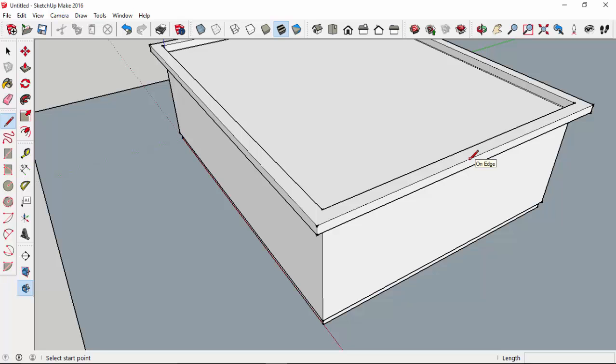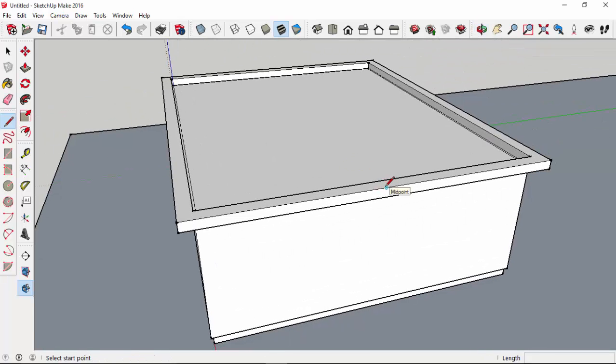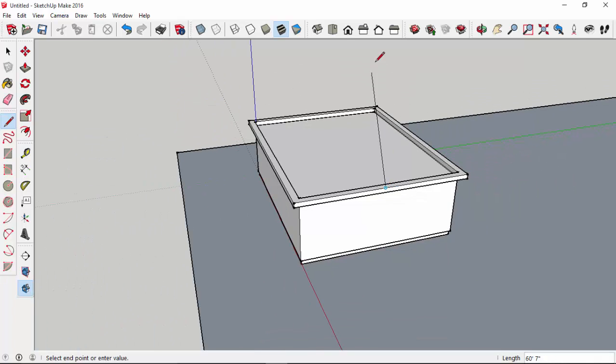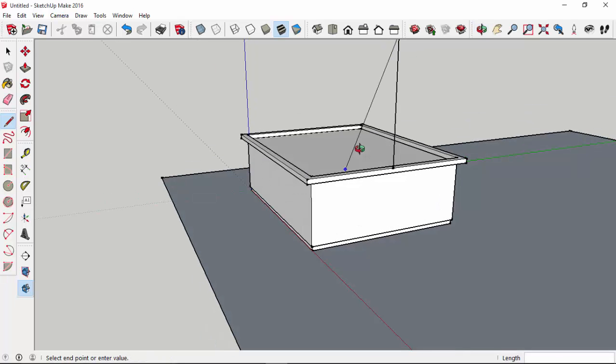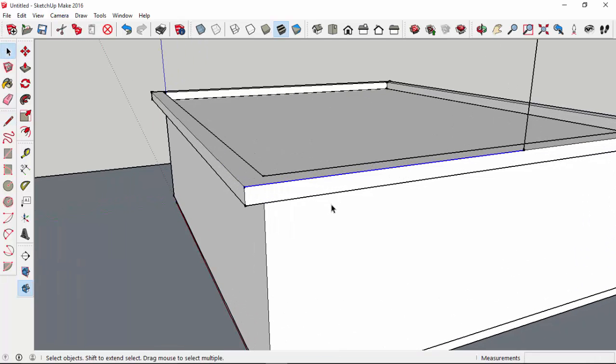And then on capes, the pitch of the roof is what I go for next. What I like to do is find the midpoint of the gable end, and I'll just draw a line that's a lot longer than I'll need. And then selecting this line here, I can rotate it. And then you can see the compass here. So I'll put it on this face, and if you hold shift, it will keep that. So then I go to the corner,